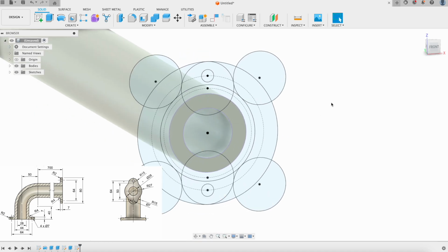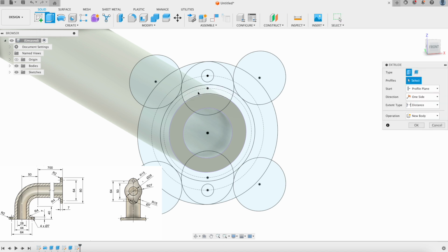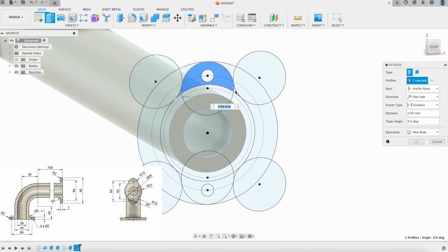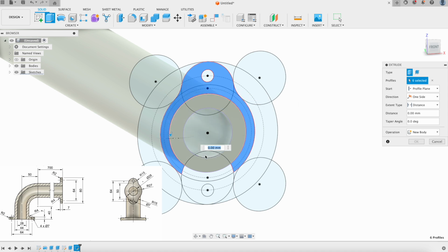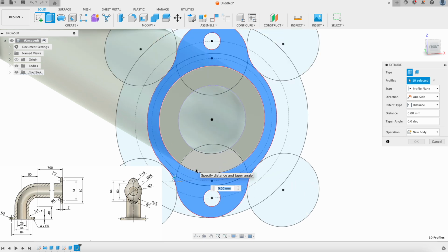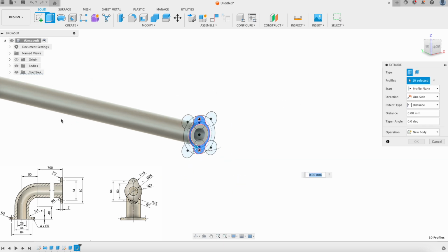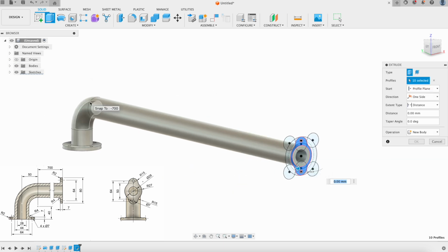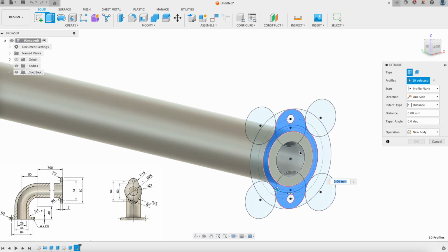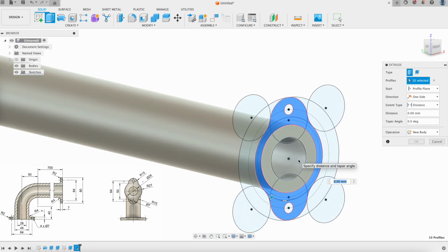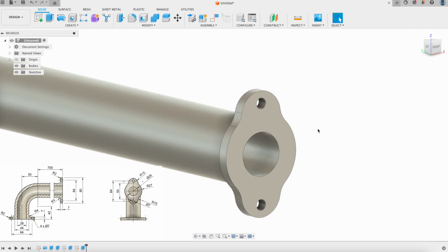Okay. To extrude this one also has a thickness of 7. So we could go ahead and extrude this portion, this portion, this portion, and all these portions around the outer edge of our pipe, just making sure to get these little kind of nooks and crannies in the center there. This one also goes back by 7. Again, notice that the 700 millimeters goes from the very corner of our pipe here, where this bend changes into a straight shape, to the very edge of our pipe. So that means we have to extrude backwards by 7 millimeters. Okay? And now we have our pipe shape.